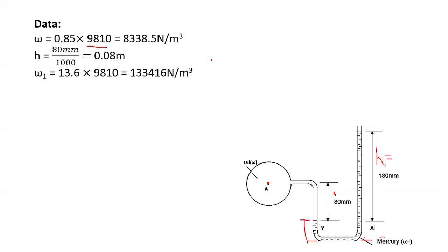Since we're looking for the specific weight of that substance, we just cross multiply, because the specific weight of water is 9810. This is one item that we discussed when we were dealing with the properties of fluids. So you don't need to worry, we just multiply by that and we are there.